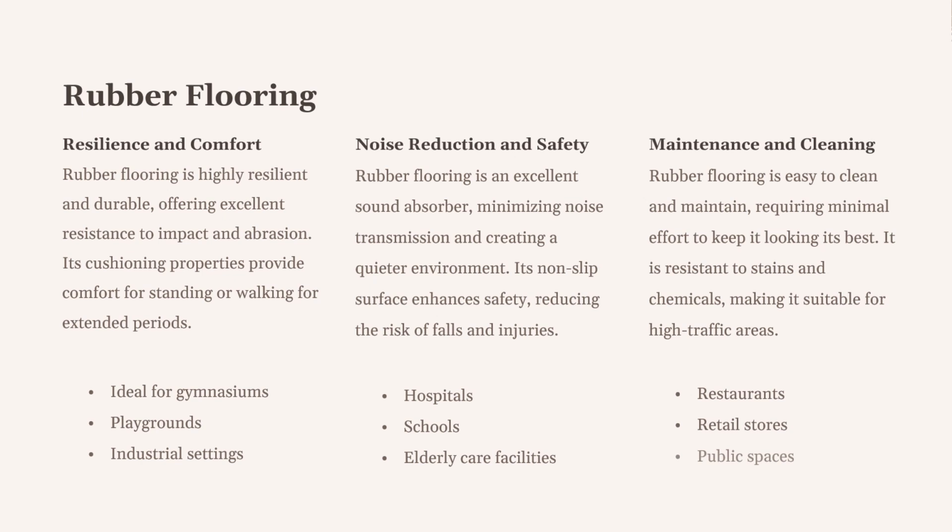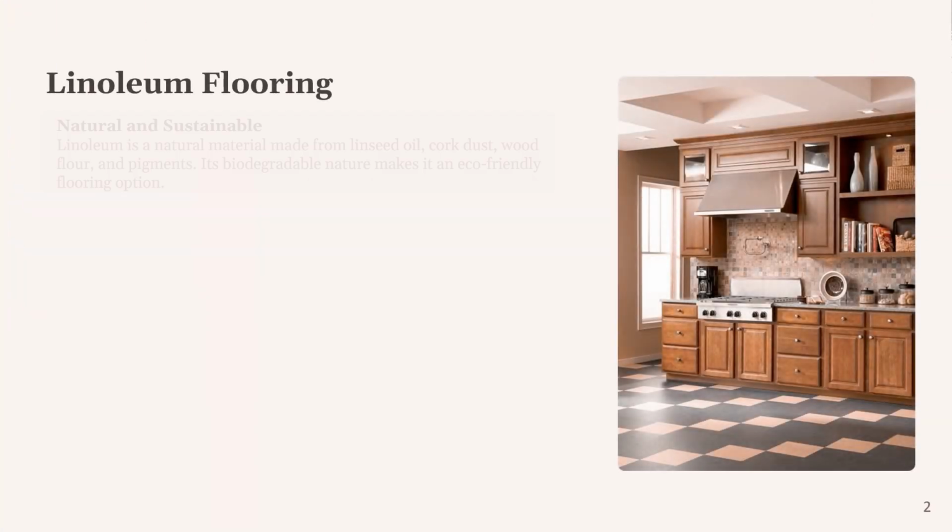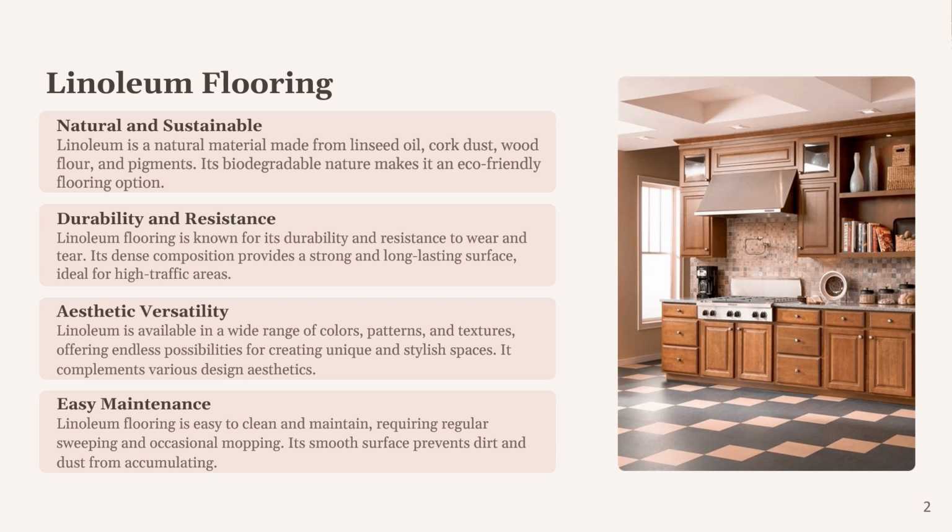Rubber flooring is known for its resilience and noise-proof properties, though it is relatively expensive and typically used in office or public buildings. Next, linoleum flooring, often classified as a covering, is available in rolls and can be spread directly on concrete or wooden floors. It is manufactured by mixing oxidized linseed oil with gums, resins, pigments, wood flour, cork dust and other fillers. Linoleum sheets are available in plain or printed form with thickness ranging from nearly 2 to 6 mm and roll widths from 2 to 4 meters. They can be glued to a concrete base or wood floor in various patterns.